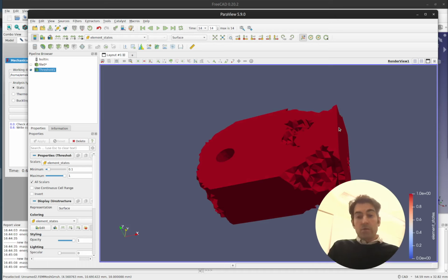So you may say, whenever I want to apply a force in a particular part, I want to have this already not in the design domain. Then you can also have another additional layer here, and in this layer define another non-modified part, and then add these parts more and more into the graphic user interface Beso algorithm. So you can have non-modifiable objects if you just exclude them from the design domain. In this way you can really do sophisticated optimization scenarios.